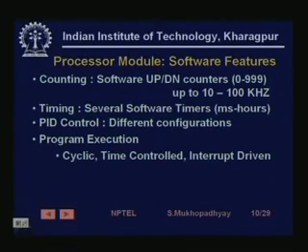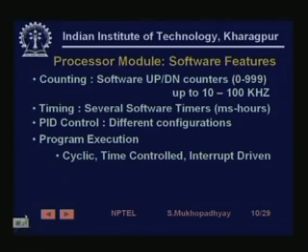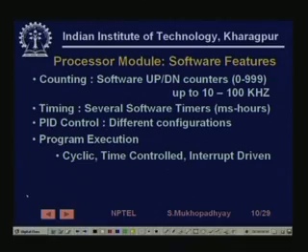The program execution in these systems is very interesting. There are generally 3-4 different types of program execution modes specified. For example, a mode could be cyclic. By cyclic we mean that you have a number of computational tasks begin just like RLL program execution. So begin here, come to the end, start all over again. So this just goes on.